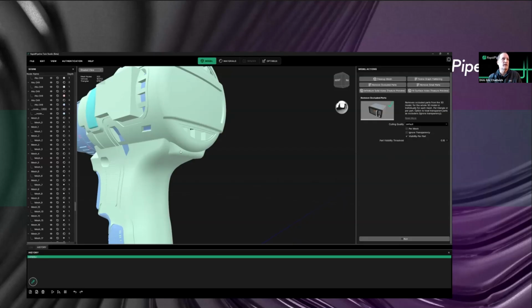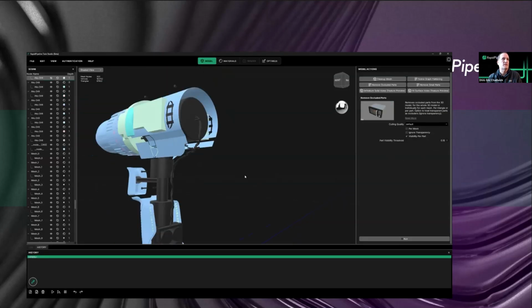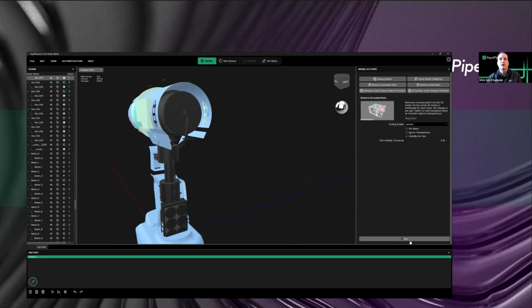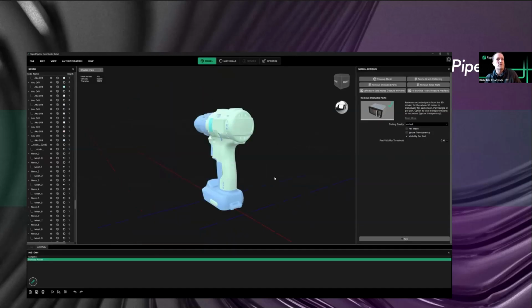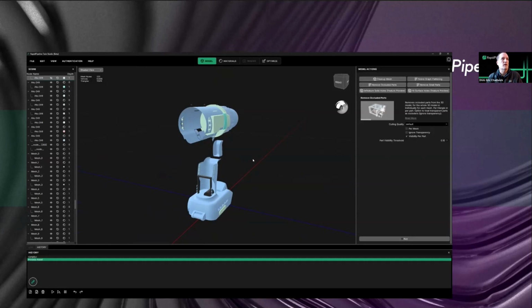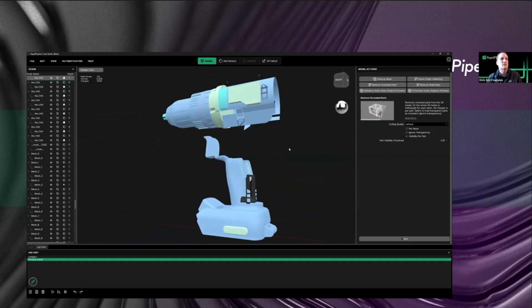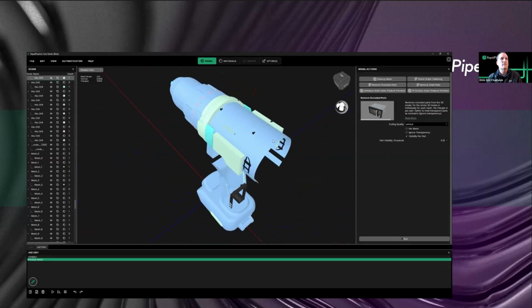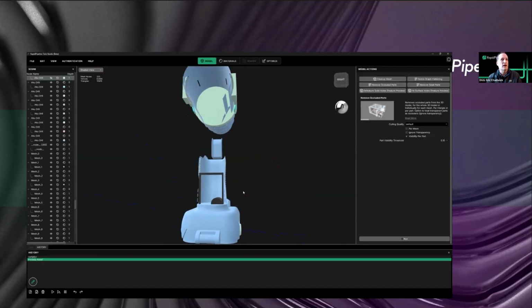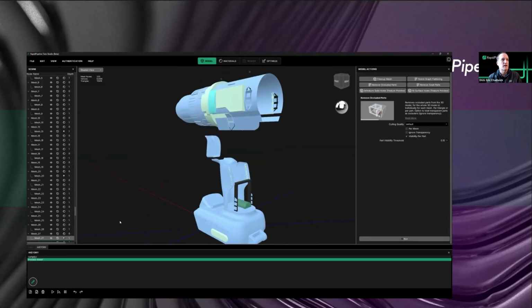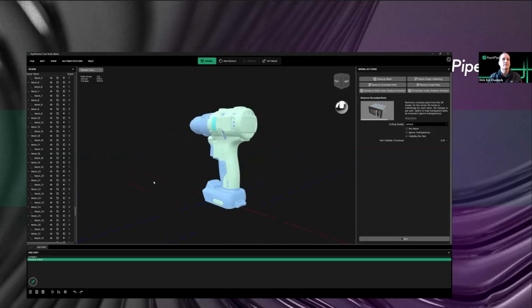So let's just go ahead and run this. If we hide this piece, just so we can see what's going on. If we cull it at the defaults, let's see what happens. It does compute the visibility for each mesh, and then pulls the model back in. And it's removed some of the parts, but it hasn't removed all the parts. So some of the parts are still visible. We've got some screws here that were probably visible through gaps in the mesh, and we've got some of these other parts inside. We can undo that to get back,